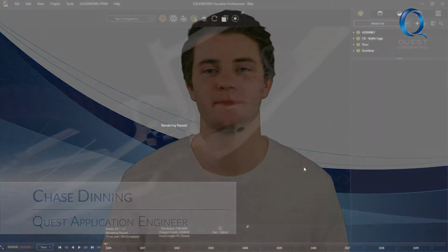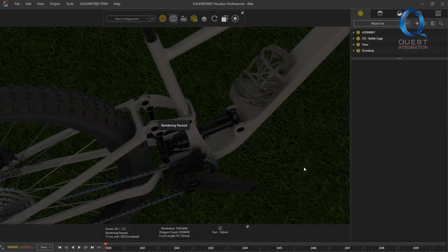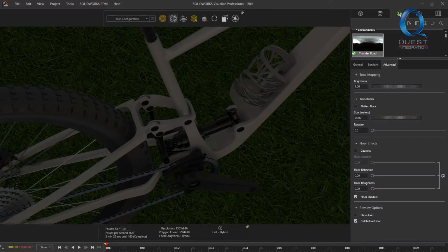Here's today's tip. There's a tool in SOLIDWORKS Visualize that I think is underused. It's fairly simple to do and yields an interesting result and great looking video. It's the sun study render option, which allows you to create a short clip of your product with the sun passing over it, giving different reflections and shadows depending on geometry.